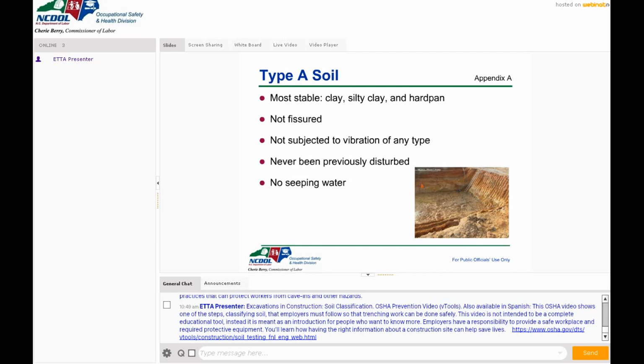Like in this particular one, you've got different soil mixed in. And don't think you won't run across A soil over C soil, or C soil over A or B. You may run into situations where, based on the angle of the dirt, say A soil, you slope it here, you might have to tilt the slope more, and then even more if the soil is different at each of the heights you go down to.